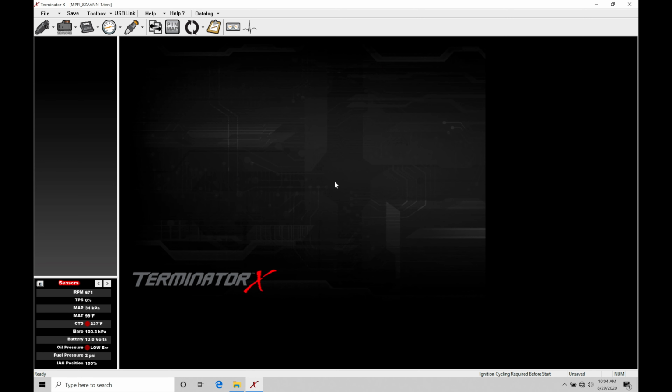We're going to be taking a look at working with the advanced fuel and spark timing strategies that we have available within our Holley Terminator X software. We know that our main fuel and spark timing tables are where we source the proper amount of fuel injector pulse width from, and also the commanded spark timing the engine needs to run. When we get in a variety of different conditions based on air temperature and coolant temperature, we can offset the amount of fuel or spark timing that's delivered from the compensation or modifier tables we've already discussed in some of our previous videos in our training course.